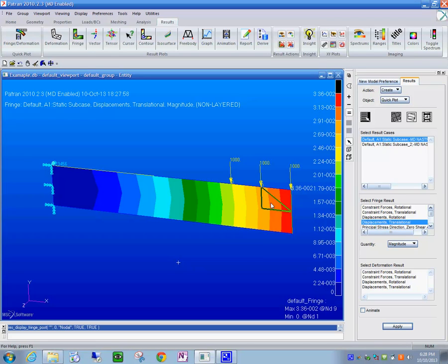They are generated by 2 points that cross the sides of the triangular finite element. And if you do the same thing to the neighbor, then pretty soon you can define the region that has the level of deformation or level of stress by coloring it. So that's how those fringes are generated.